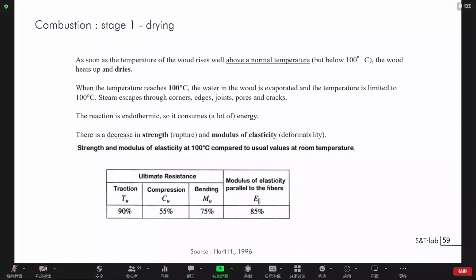I have to put forward that depending on the temperature, in the first state, you remember that temperature in timber was raised up to 100 degrees. You also have a loss of properties in timber itself, but you know that these 100 degrees are not met all inside the structural member itself.